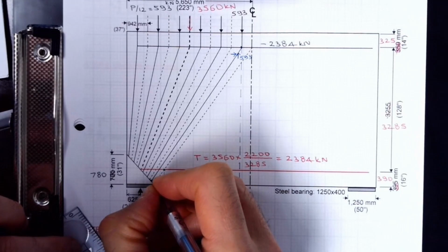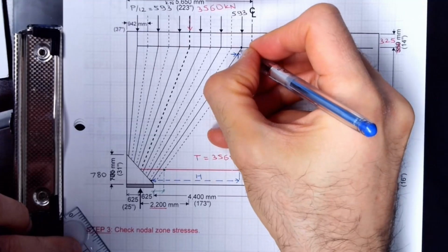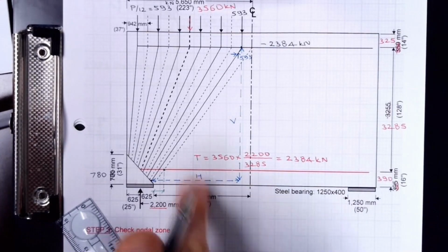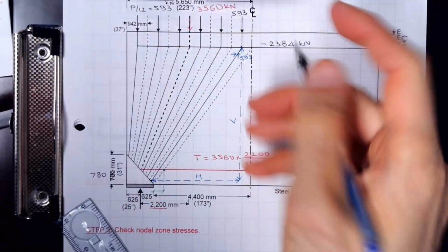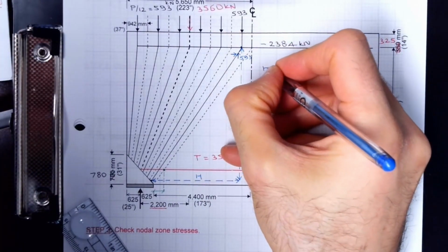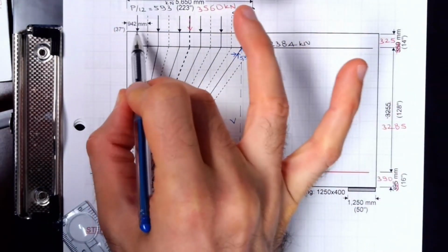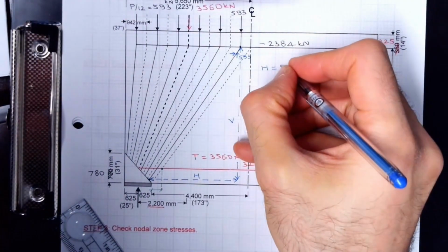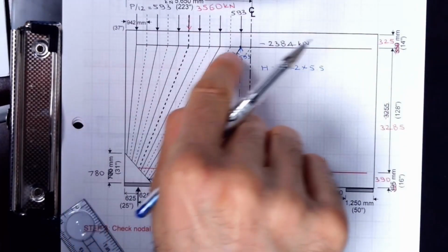In terms of distances, I'm going to call this one H, and this one V. First of all, let's calculate H, because once I isolate that triangle, that's what I need, nothing else. Of course, if you are using software, you would get this right away, but I'm just using hand calculation. Tributary distance, if you divide this by 6, you get 942 millimeters. So 5.5 times 942, because it's equally spaced and I'm here, so I'm using 5.5.